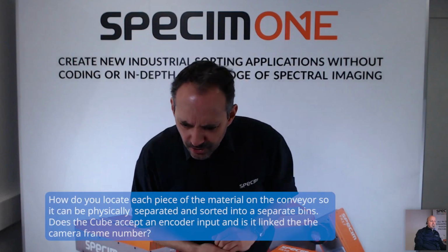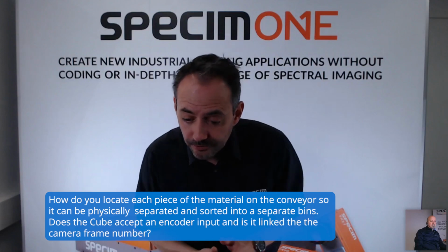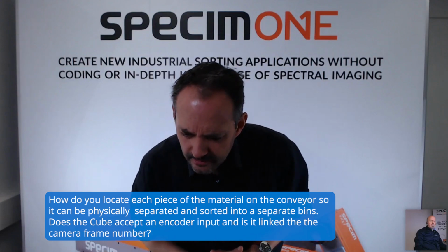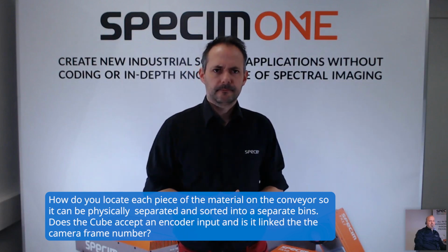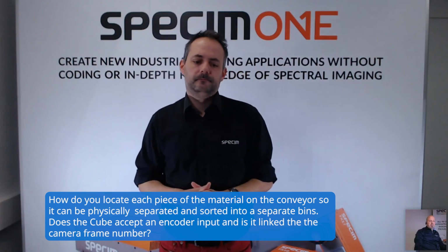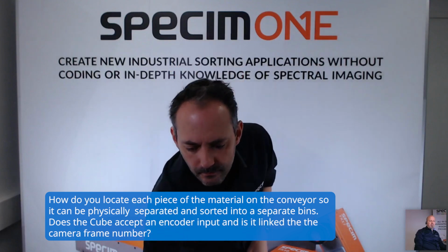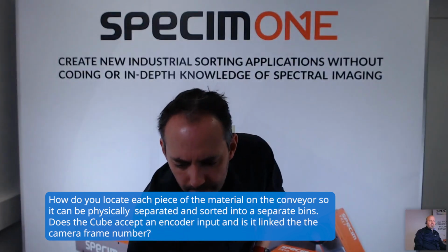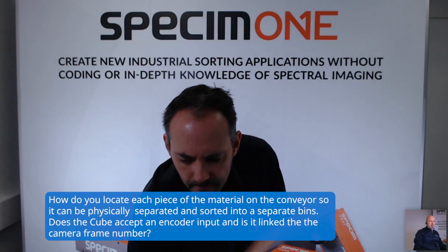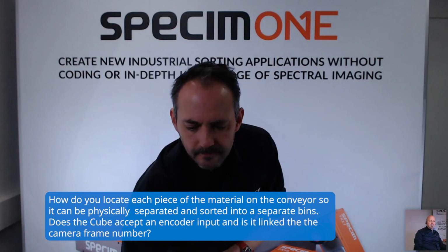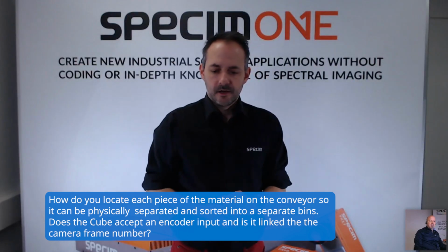The next question, Jörg, do you want to answer? How to locate products on the conveyor belt? Yes, the cube has an encoder input, so you can synchronize with the speed of the conveyor belt, and then you are able to pick or blow out the products. That's easy. Okay, thank you.